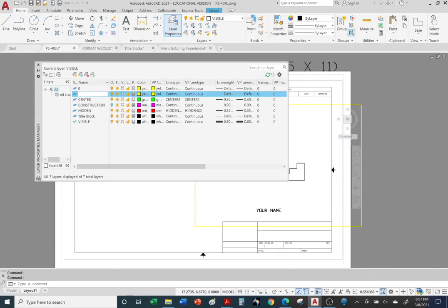When you're typing in a name, there are certain things you can use, like symbols. You may not be able to use spaces, so keep the name of the layer simple. Avoid using symbols or spaces, or else it may reject the name you give it. So I'm going to keep it simple, viewport, and then click away.